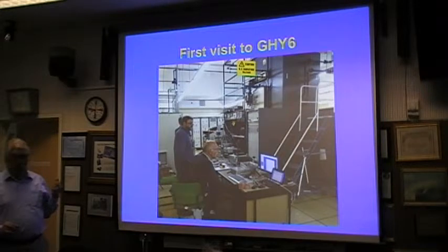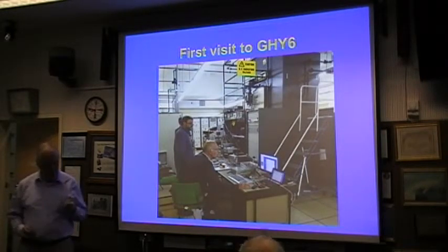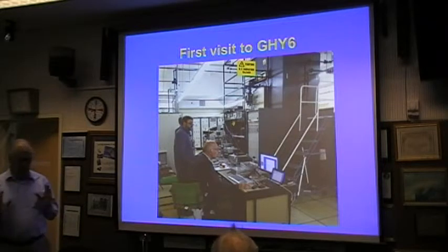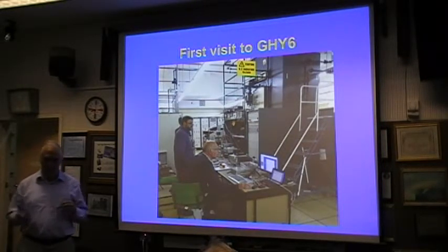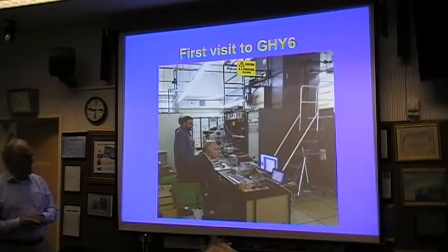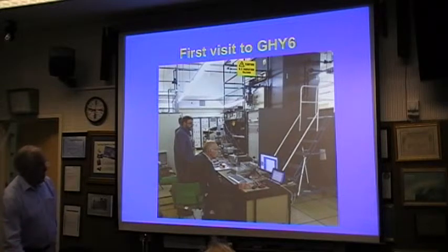We measured the return loss on transmit, and on 3.4 gigs it was 8 dB return loss, not very good. But luckily somebody liberated some circulators from somewhere, so we were at least able to protect the PA. We fired all this up, and we were getting massive echoes off the moon. What a surprise, with 50 watts. And this, I think, is probably one of the early attempts where we were trying to make things work.